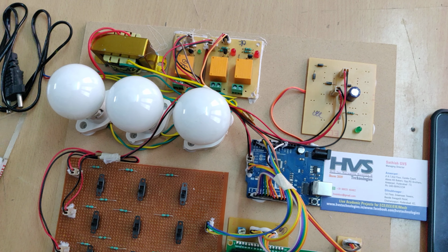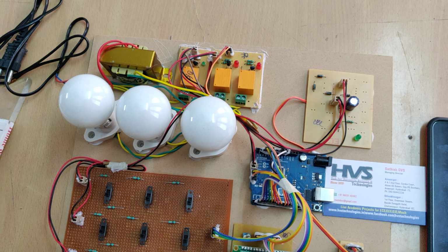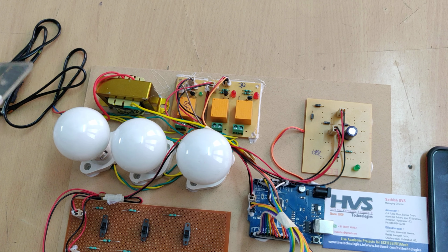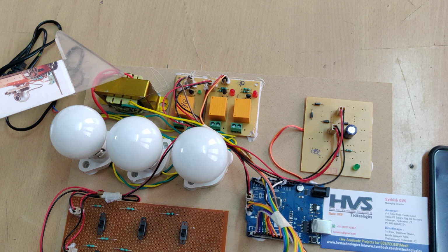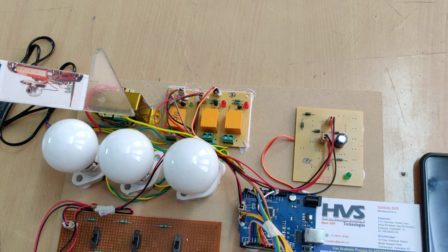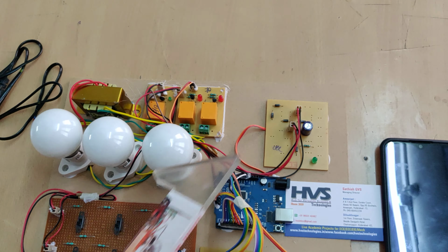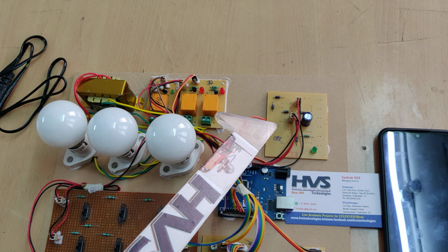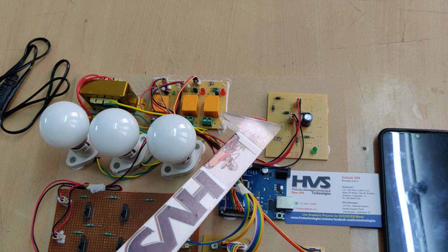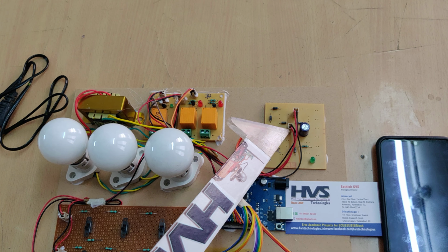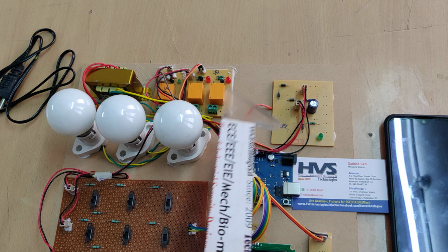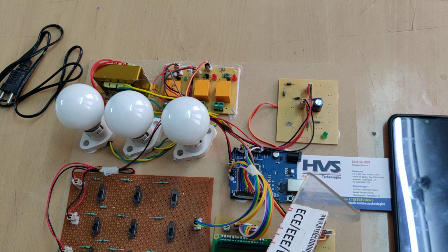Here we are making use of 3 electromagnetic relays for 3 phases. We are providing 230 volts as a single phase input, but in real time we can provide 3 phase inputs. This 230 volts input will be converted into 12 volts AC, and this 12 volts AC will be converted into 12 volts DC with the help of this regulated power supply board. After this we get a constant regulated 12 volts power supply, which is given as the power source input to the relays as well as to our Arduino UNO board.